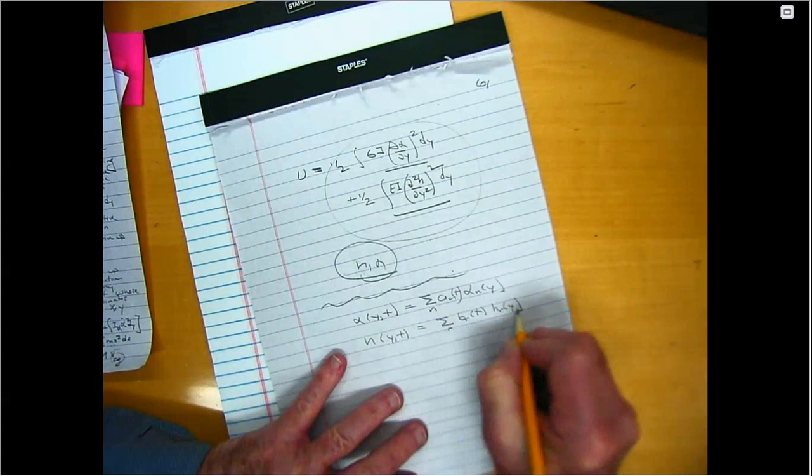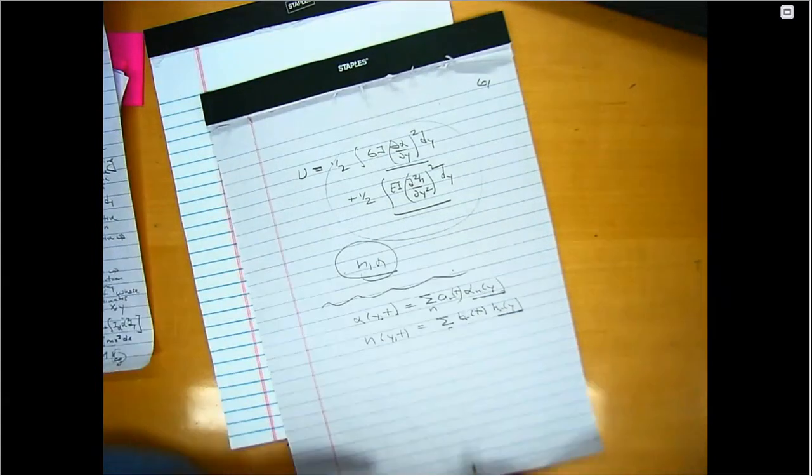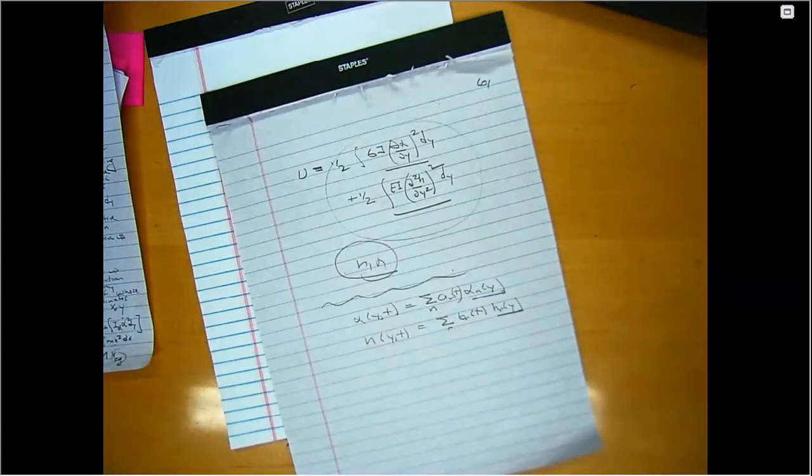Of course, I have to determine those modes. And what we normally use are the natural modes of the system. Those are the modes that occur when I set all the aerodynamic terms to zero, right? Those are the natural resonant modes of the structure. That's what you universally use if you know them.